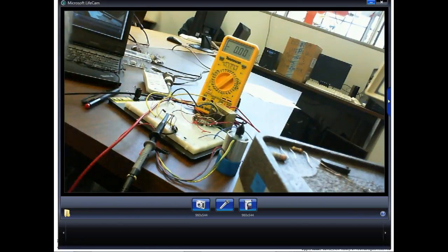They think they can just take a meter. Now we got 2 voltages in the circuit. We got an AC voltage on one side of the diode. We got a DC voltage on the other side of the diode. So my meter's taking the DC average of a cycle. What's the DC average of a cycle? 0. And that's why we have to use the root mean square, the root of the means of the squares, right? You understand, to get that effective voltage. So RMS gives us the effective voltage where the negatives do not cancel out the positives.